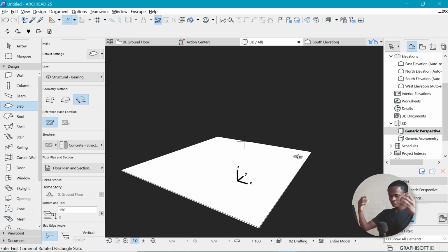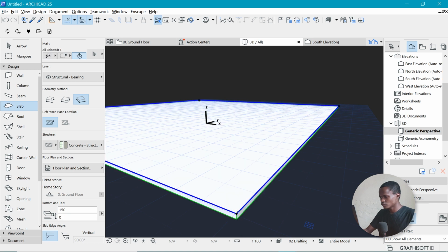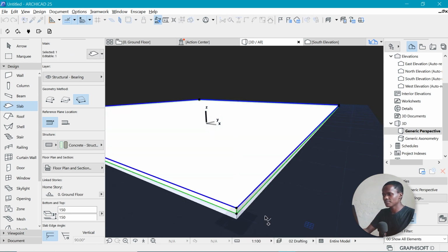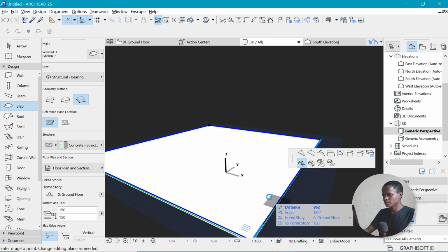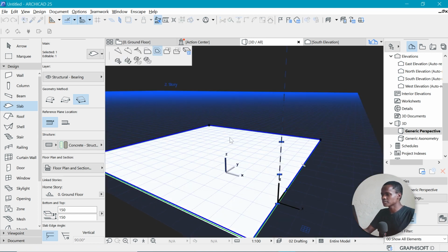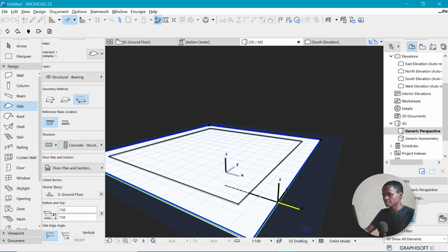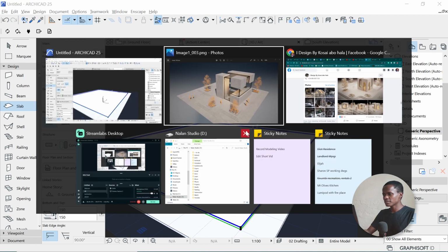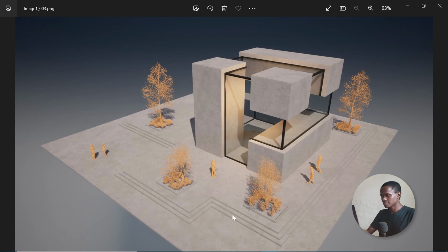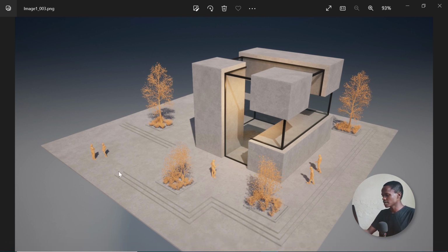So now let's create those steps that we are seeing. So let's make a copy of this, Ctrl+Shift+D. I'm going to make a copy of this up here, and I'll scale it down such that the building will take a smaller portion of this side. So something like by 2 meters, I guess, something like that. And we want to be able to chop off these things which you're seeing, like this part. We remove this section and remove this portion as well.